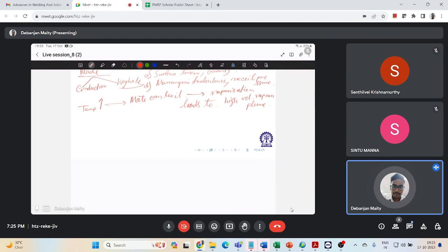Now, I have mentioned these two common techniques of laser melting in powder bed fusion systems. Those consist of continuous wave and modulated melting. In continuous wave melting, the laser irradiates the metal powder under a constant flux as it rasters each layer of the build, and the scan lines comprised of molten and solidified melt pools will overlap on each successive pass, which partially remelts the previous raster line, right?